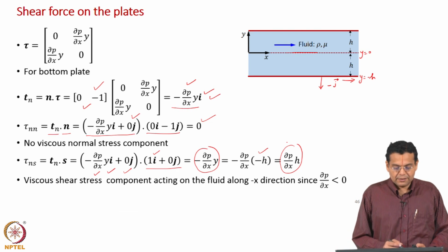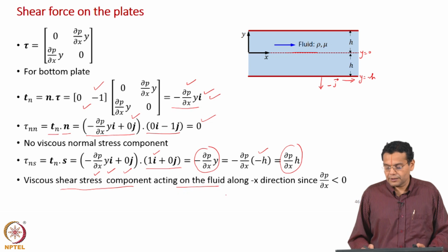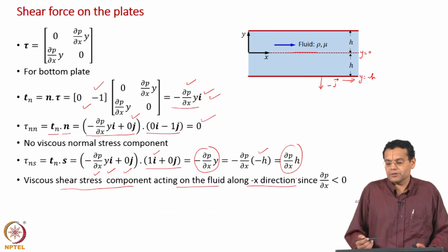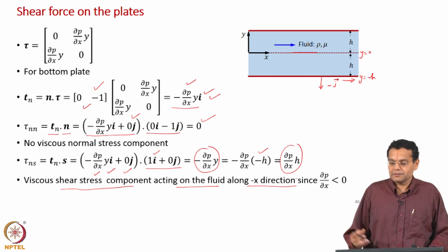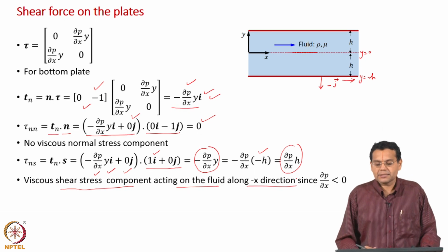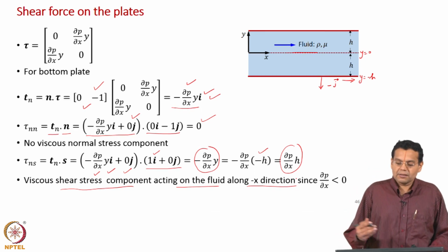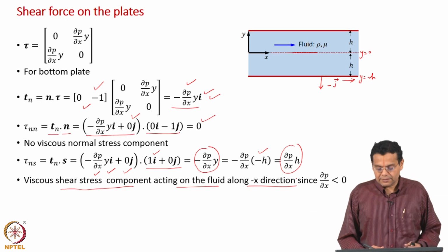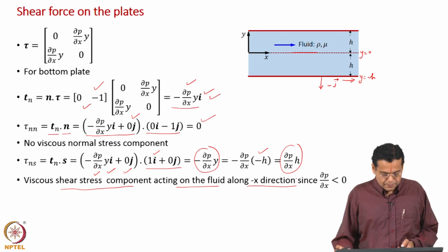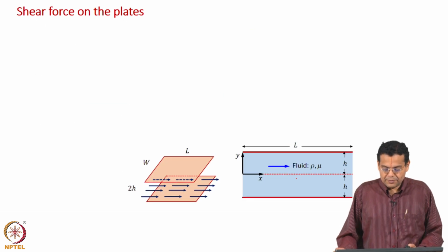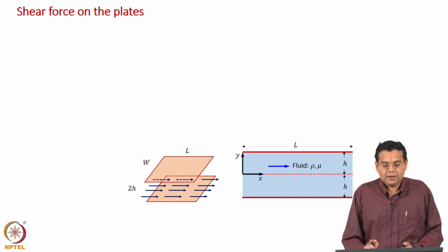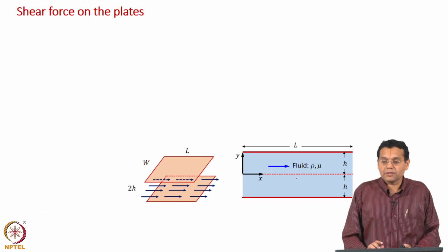So, here again the shear stress component acting on the fluid is along the negative x direction. Of course, that cannot change because through the entire domain fluid flows along the positive x axis. So, certainly the shear stress acting on the fluid is along the negative x axis. Now, what we will do is find out the shear force on the plates.